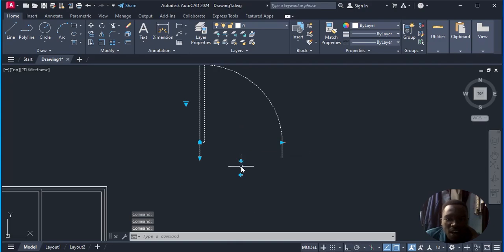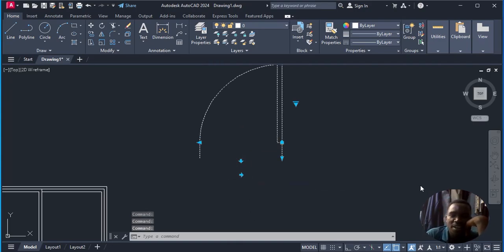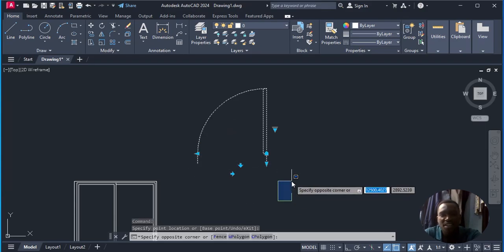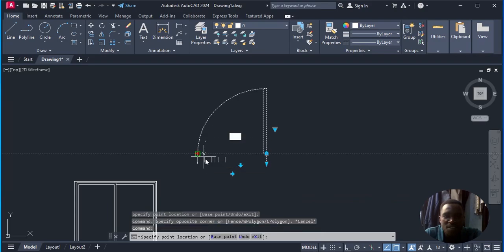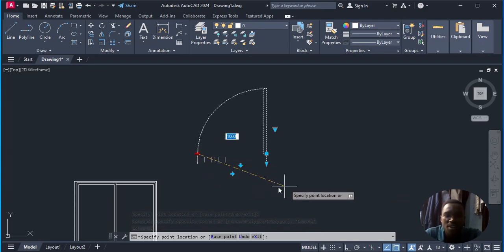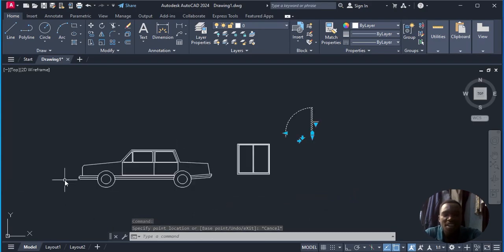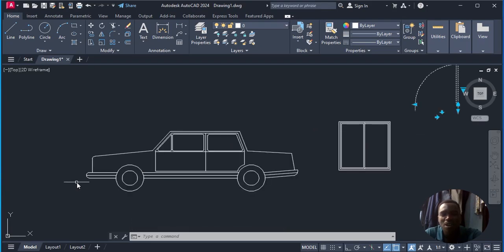You can, let's say, want it up. You can say let it face down. Also this one, we can face in the left. We can also make it face in the right. And then there is also this one. This arrow shows the length of the door. We can push it, let's say, to 1,000. And everything is set. So if we are to measure this here, it is 1,200. So this one limits us to 1,000. So that is dynamic blocks, which I can talk about for now.